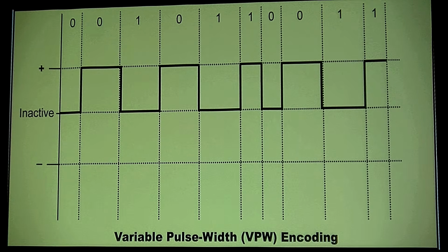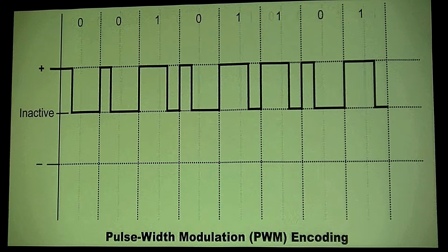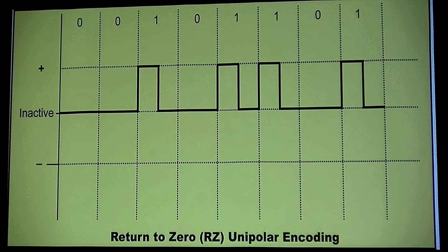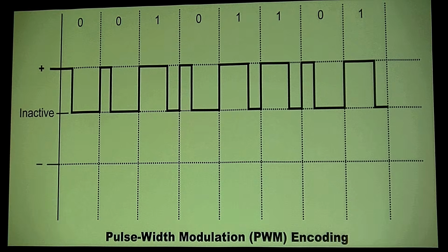He's not timed with the rest of the bus. Now he's going to start to give you problems. He's going to set codes. And I'm going to show you exactly how this happens. This is just one coding scheme. This is pulse width modulation. So this is what Ford would use. And again, it's just edges.